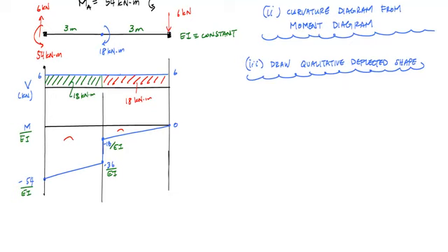So it's what people like to say, you got to do practice, right? It's all about practice. So I start off with the undeflected shape, and now, based on my moment diagram and the boundary conditions, I can draw what I think my deflected shape will look like. And I know that at the support here, I have to have a slope of 0, so I'm going to start off horizontal here, and then it has to be concave down, going all the way across.